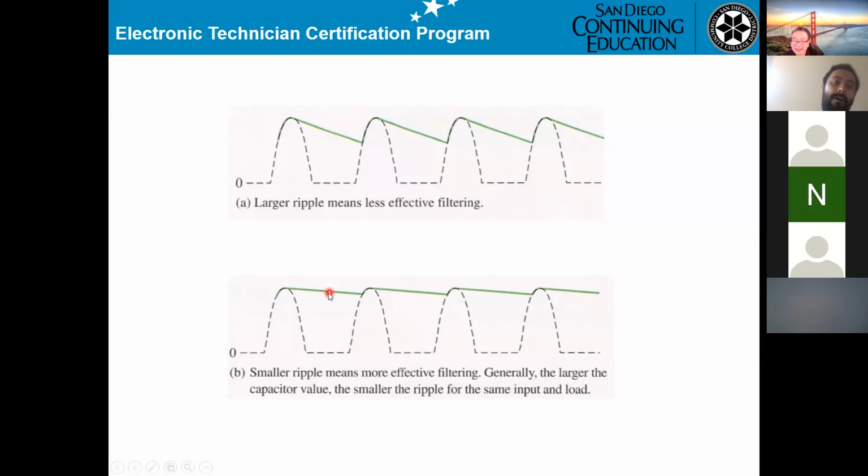Tau. This depends on the duty cycle of the signal. That means you get a square wave with the time high of 5 milliseconds and 5 milliseconds low. So it will discharge like this one. However, if you change it to 5 milliseconds high and only 1 millisecond low, then it discharges this way. Why?